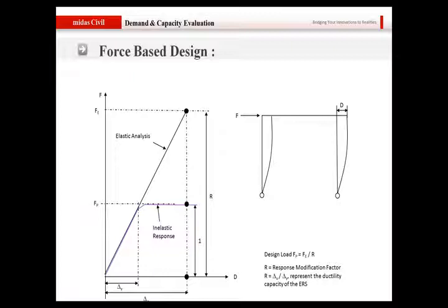We obtain the force generated by the earthquake, we obtain the effect of that force on the bridge, and then we design the structure accordingly. And the ratio of the inelastic and elastic response divided by the elastic response will represent the ductility of the bridge.